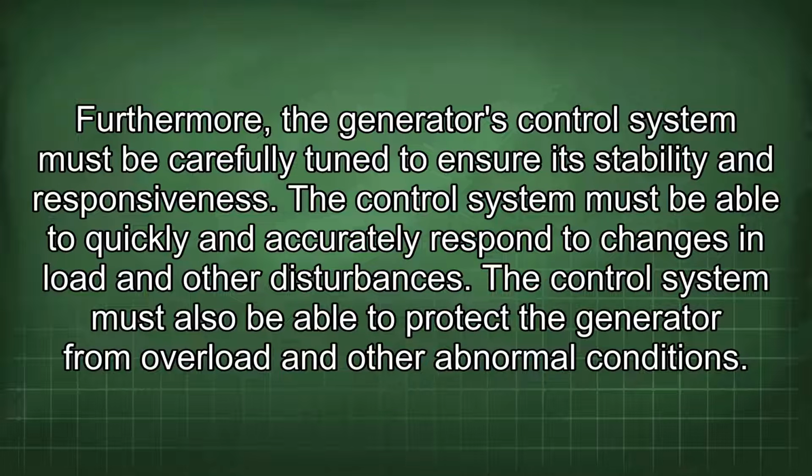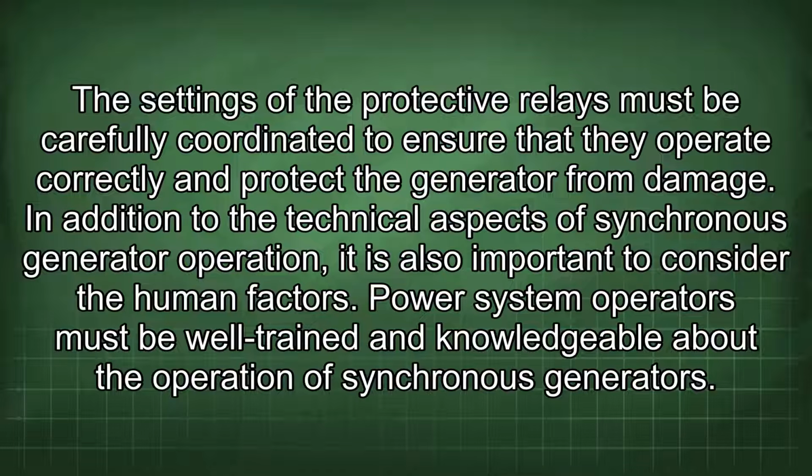Furthermore, the generator's control system must be carefully tuned to ensure its stability and responsiveness. The control system must be able to quickly and accurately respond to changes in load and other disturbances. The control system must also be able to protect the generator from overload and other abnormal conditions. The settings of the protective relays must be carefully coordinated to ensure that they operate correctly and protect the generator from damage.